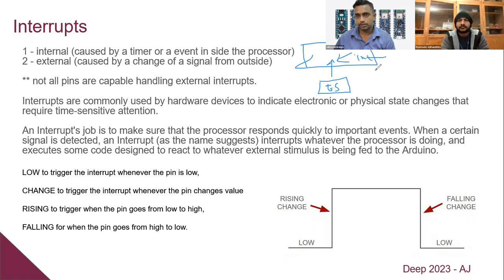This means that when you press this button, the processor stops all other operations and pays attention only to this task. Like let's say the processor has been counting something while you press this emergency stop. The processor is going to hold this operation and pay full attention to that emergency stop event, right? That's the purpose of interrupts.